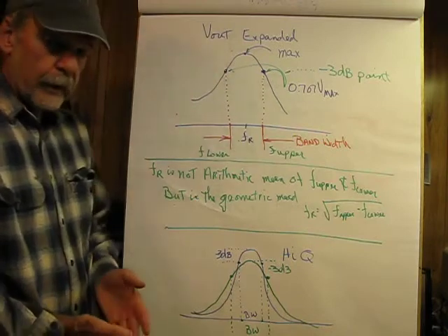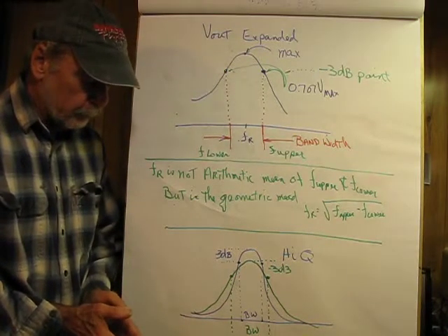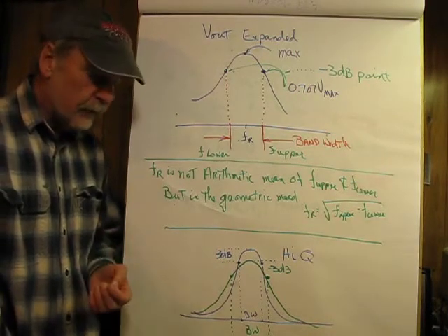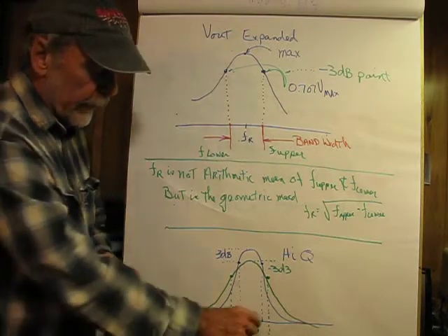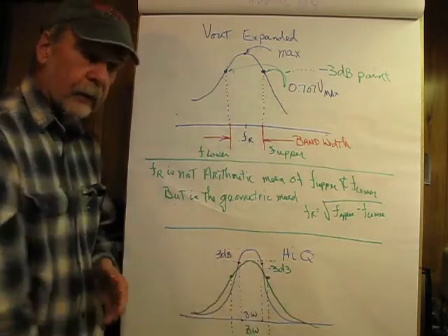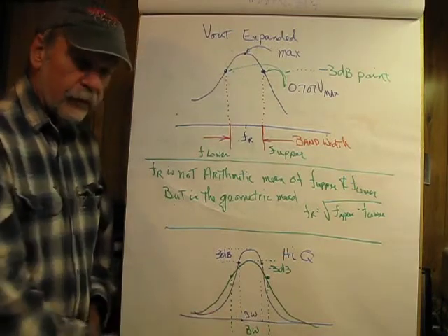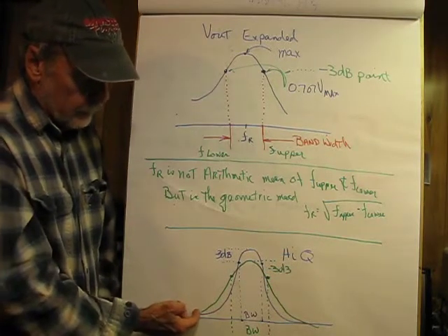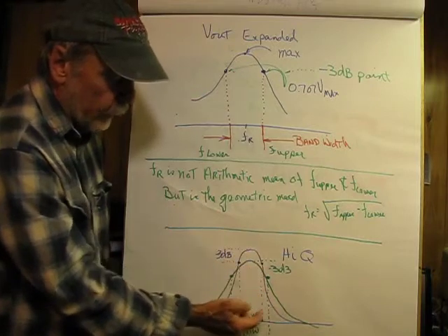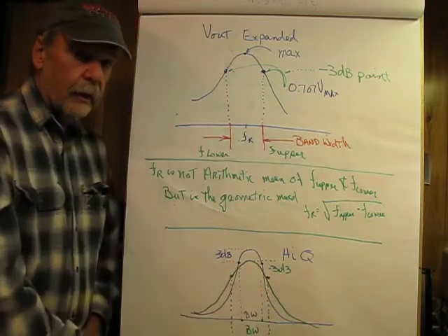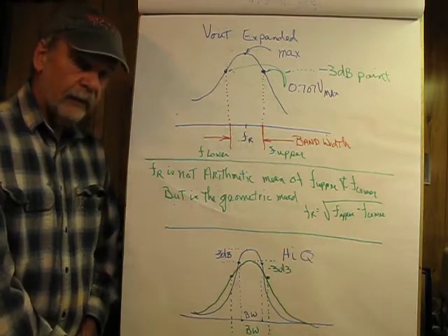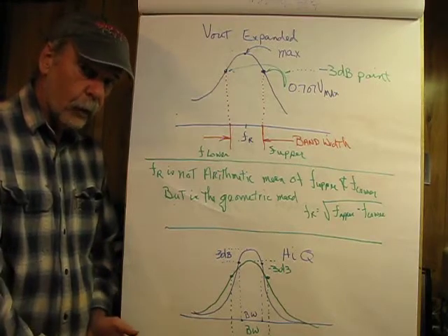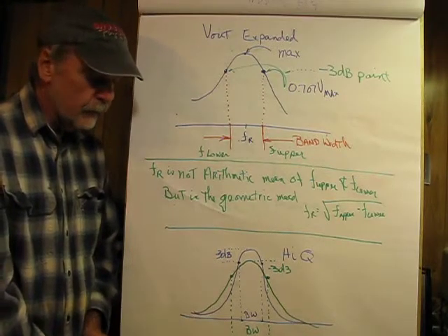Now let's think about an AM radio for a second. The bandwidth by FCC standards is 10 kilohertz, and the maximum frequency that can be transmitted is 5 kilohertz. So what we want to do is have a bandwidth that would basically be a rectangle, but we can't do that. There would be 5 kilohertz on each side, or 10 kilohertz total. Now in the practical world, if I made the Q really high, that would cut off the components of the music or speech in or around 5 kilohertz. So it would be a poorer frequency response than it is already, 5K compared to FM, which is 15K.